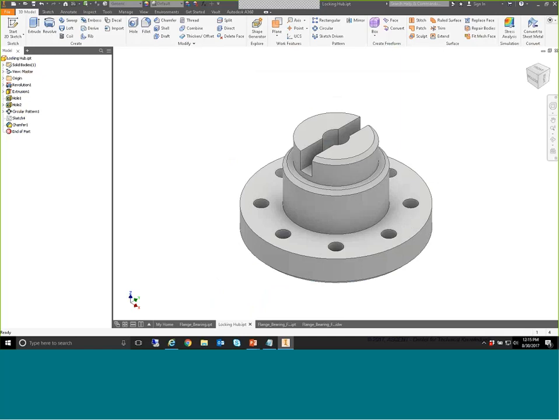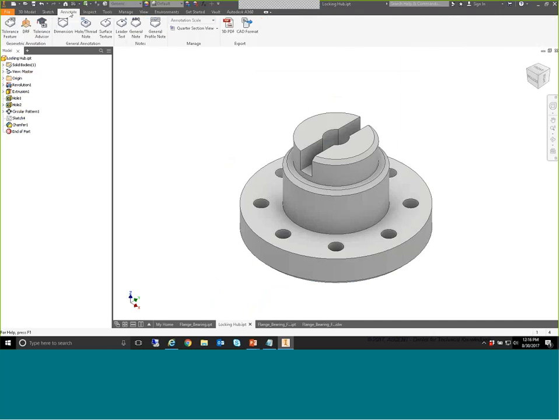So as you can see here, I've just opened a model, pre-opened, so we don't waste time doing all of the opening. There's no annotations in it. You can see that those 2 folders that get created aren't here, so I haven't actually done anything in this model yet. So I can open my Annotate tab by selecting Annotate on the ribbon, and you can see all of those commands that will allow me to create my annotations are in here.